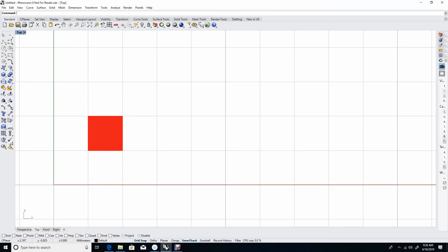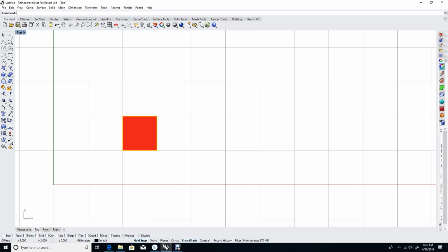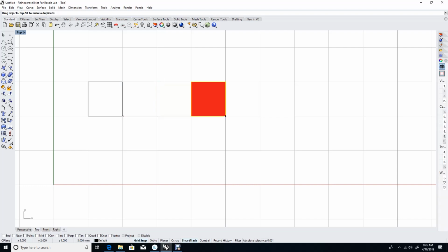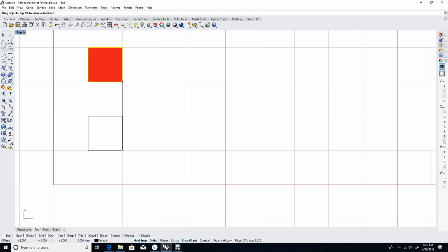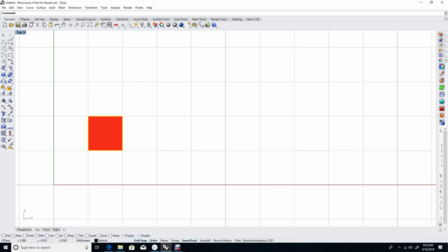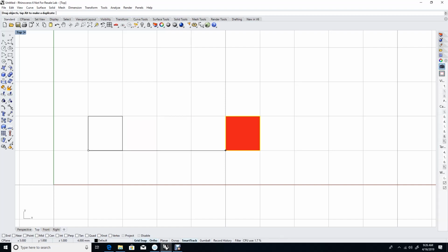In a typical 3D modeling environment, such as Rhino, you create objects interactively, and then you can move them from one location to another using visual and modeling aids. For example, you have a grid. You can snap to that grid, and you have things like the ortho to constrain my movement in certain direction, and you can snap to other objects. All these modeling aids eliminate the part where you have to explicitly describe the movement from one location to the next.